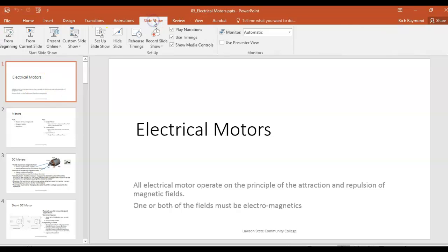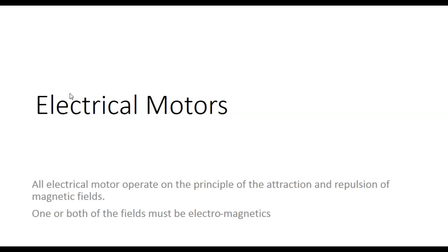So here we go. Of course, all the motors on our manufacturing line are DC. You'll run into both of them in industry though. DC used to be the predominant motor for speed and torque control. So what you'd do is take AC, convert it to DC, what we call a DC drive, and then use the DC drive to run the motor. And you could run it at any speed you want, from no load to full load. Very reliable depending on what type of DC motor you have, and you can control it precisely.